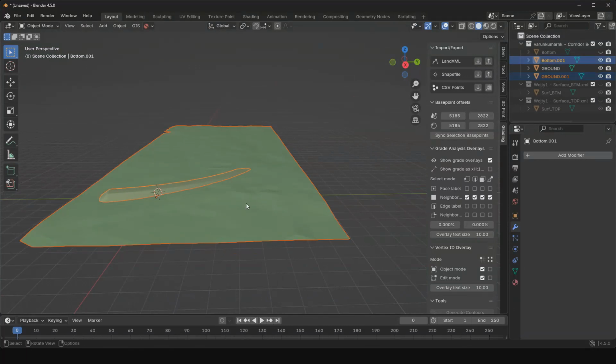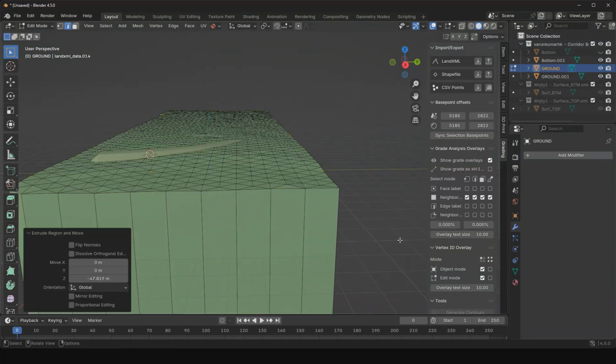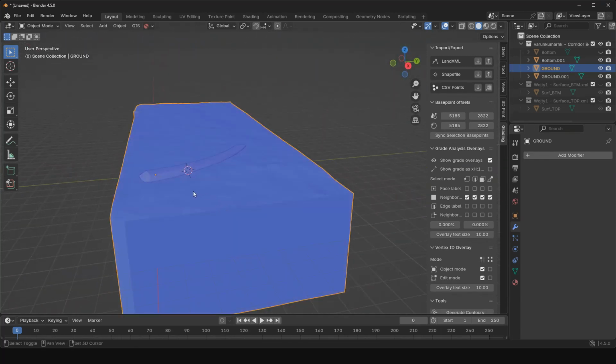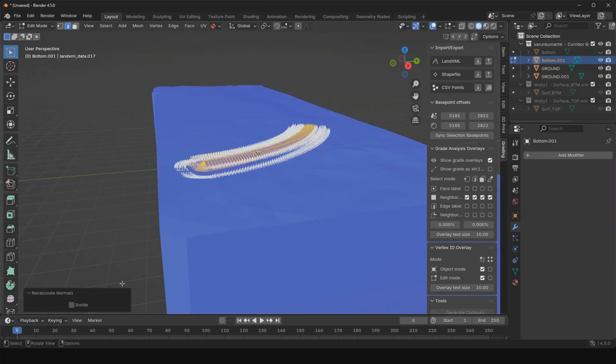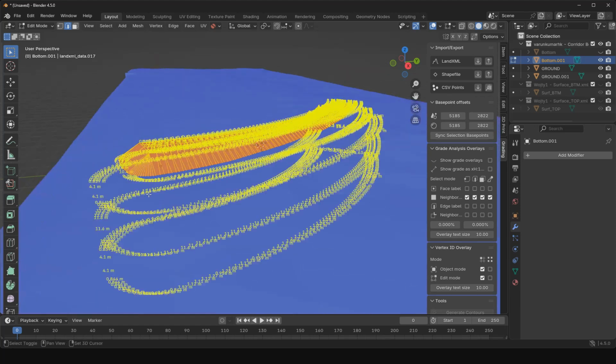Duplicate our topography also, and make our topography or existing ground also a solid. Check the orientation of the faces. That means that you can have in Blender an object where the inside is on the outside, if that makes sense. So red would be incorrect here.